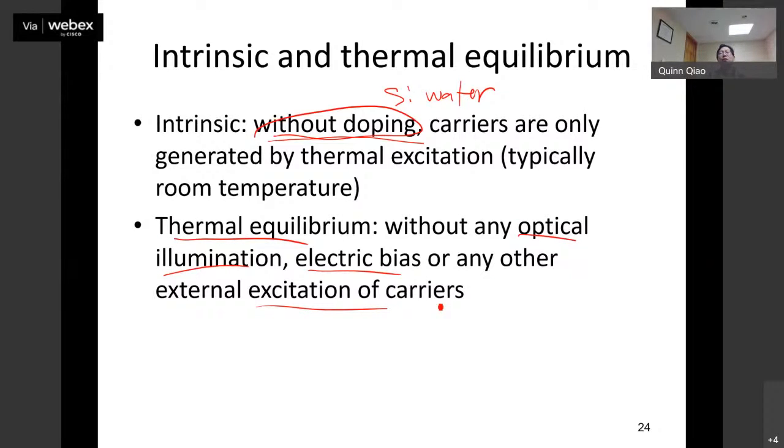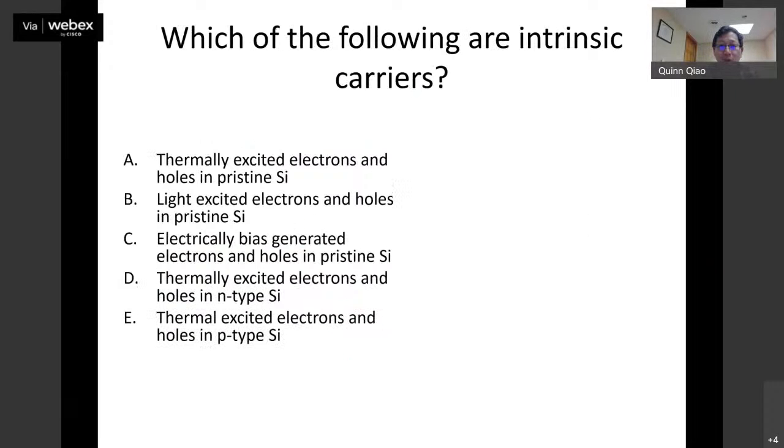Yesterday we talked about bias, right? You can add in the optical bias, where they shine light on the device, or the electric bias, where you basically add voltage. When you don't have any bias, either electrical, optical, or magnetic, that's called thermal equilibrium. Under thermal equilibrium, n_i squared equals n0 p0. But if it's not under thermal equilibrium, then this equation is not valid. We're not going to talk about this; you can do this by yourself, right?